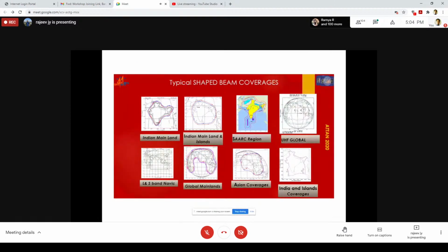We also use dielectric resonators. We also deployed them at low frequencies, we have used air itself as a dielectric, and used cross dipoles. So various types of arrays. But now I am going to talk about reflector antenna technology, because as I was telling earlier, the shape of the beam is very important.